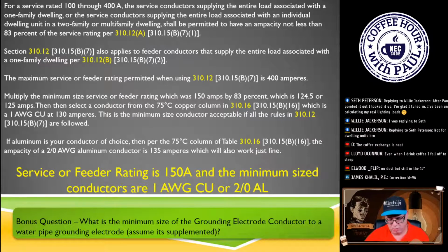People ask me, when do I apply 310.12? The answer to that question is, whether you're on an exam or in the real world, you will always apply 310.12 as long as it's applicable. The service rating, in our case, doing a service, is rated 100 to 400 amperes. Of course, to use the optional method it would have to be over 100 anyway. It's a single phase, 120/240, so we're good there. No problems with that.